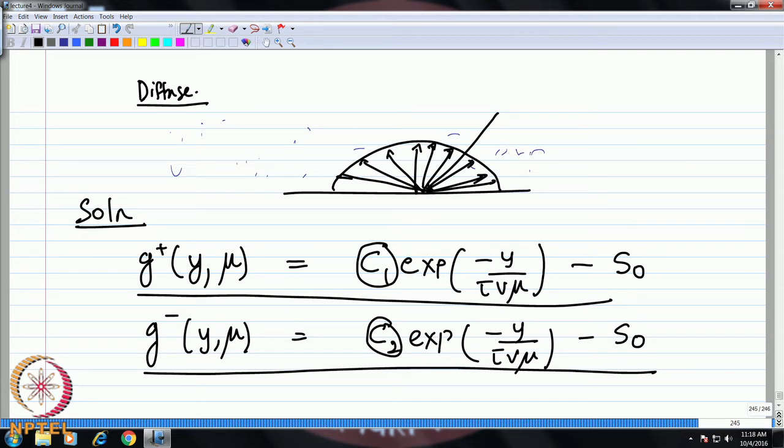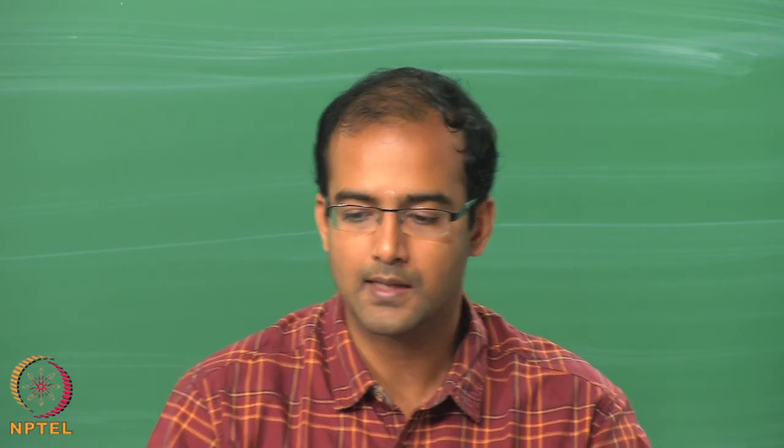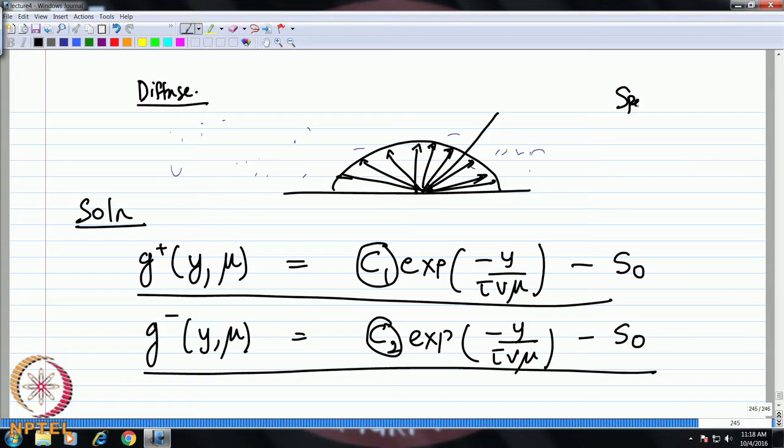So, this is quite similar to your radiation transport. In radiation also you have a particular intensity of incoming wave which hits the boundary and can get scattered or reflected. So, we have two different kinds of reflections. One is a diffuse reflection where the intensity of the reflected beam is uniform, the same magnitude and uniformly spread over all the directions. Okay. This is similar to the diffuse scattering we are talking about here. The other is specular.